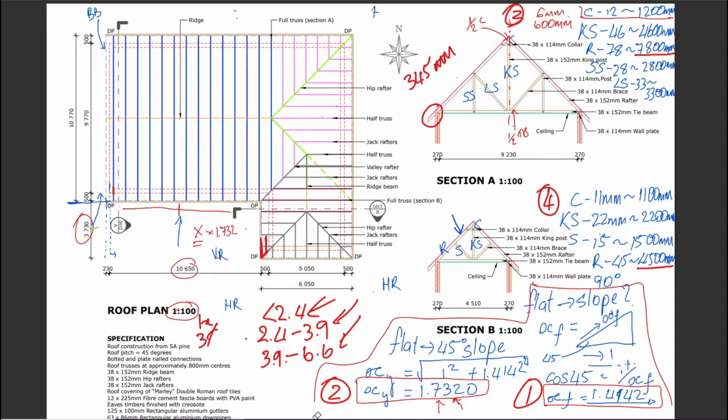As for the rest, it is pretty straightforward. For your roof covering, you just take that side, multiply it by your gable end, and remember at the end of that huge description for a roof tile, you need to apply your factor, which I put down here. And remember, don't use this factor. That's for your rafter and your hip rafters. So you must use this factor for your standard rafters. And at the end of that giant tile description, you add times 1.4142. It turns the whole thing into slope, like this.